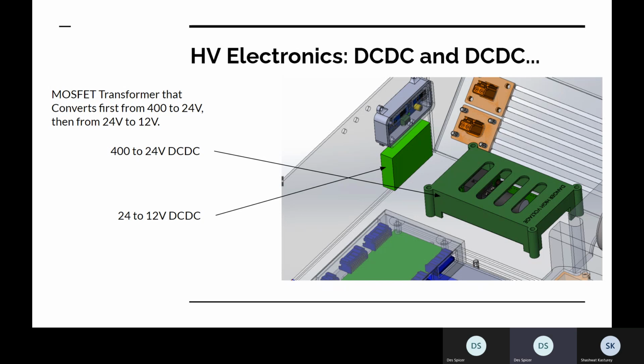It's more or less the same design methodology, it takes in the I2C, but it has controllers on it that can read at a much faster pace, so it can put out a faster PWM signal and control those fans a lot better. Plus the controllers on them are more advanced, so I can do some really cool things with them.